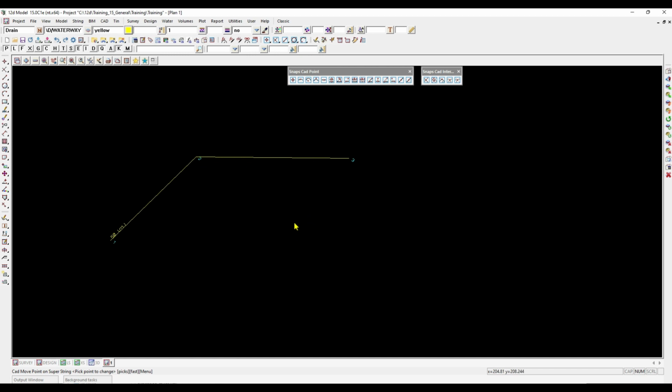And we're just going to go and look at that now. So back to our CAD vertex tool, which is 2 up from the upside down pentagon on the left. If you click and hold and go to the third one from the end, the third one from the end is insert, and we'll select that. Let's go ahead and insert a vertex between vertices 2 and 3.